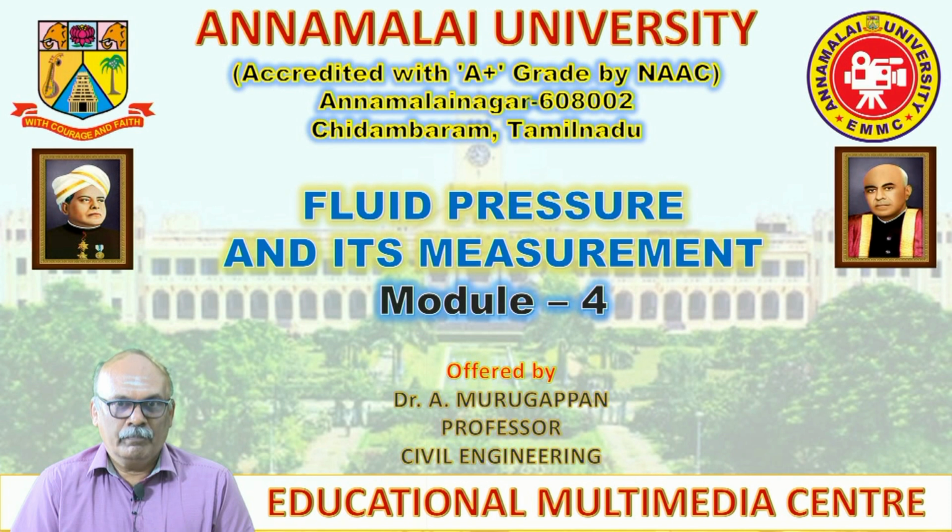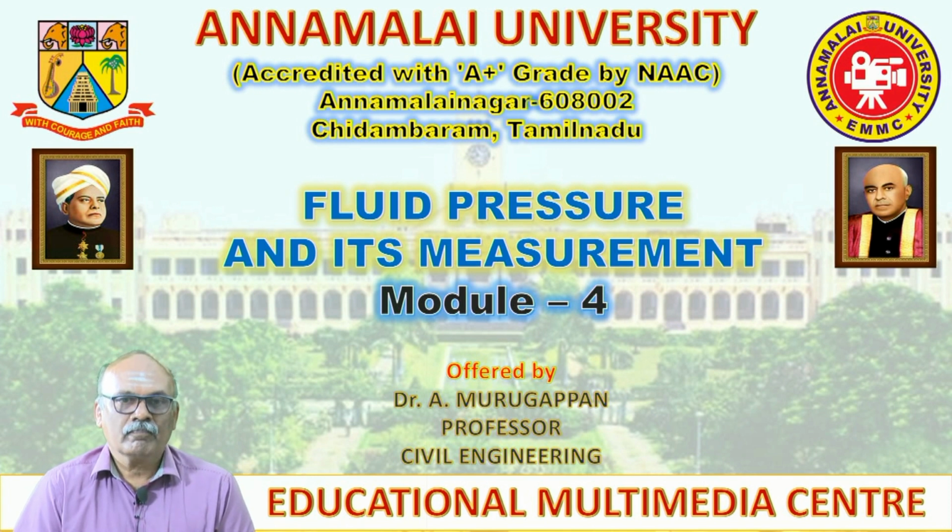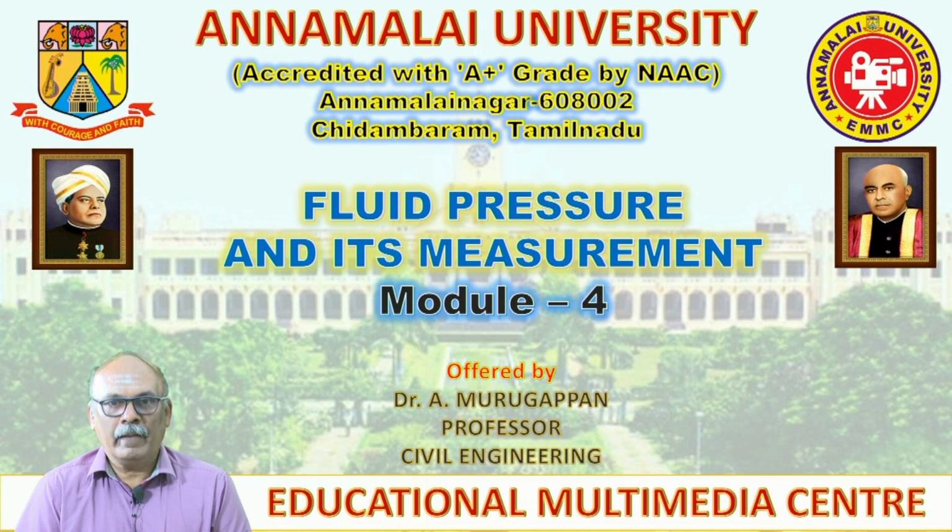Then we discussed piezometers, the simplest form of manometer we come across, and what are its merits and demerits, what magnitude of pressure it can measure. It can measure only moderate pressures. It cannot be used for measuring high pressures of lighter liquids particularly, and also it cannot measure the pressure difference.